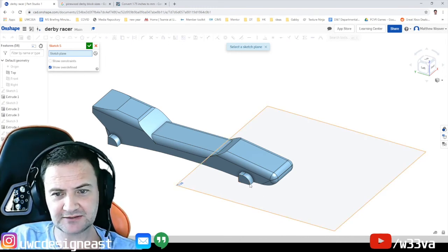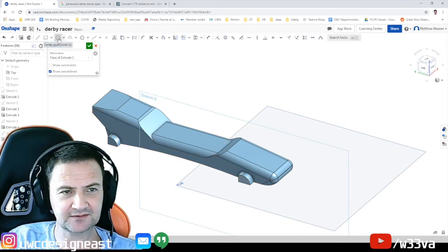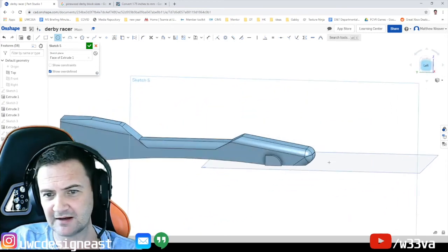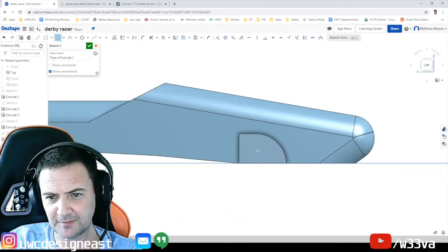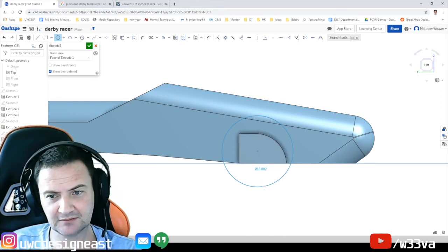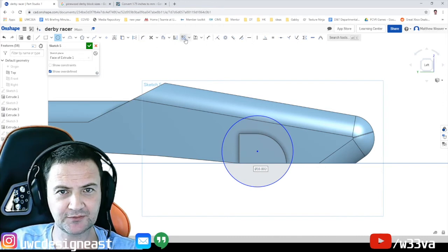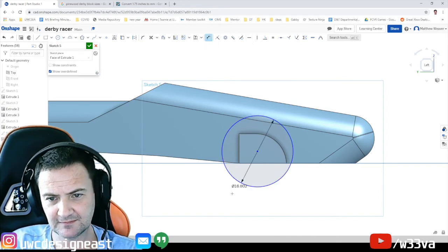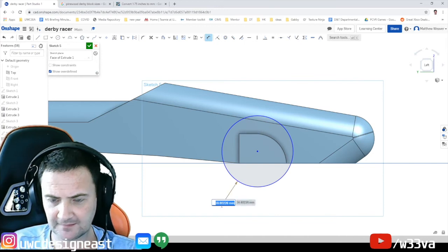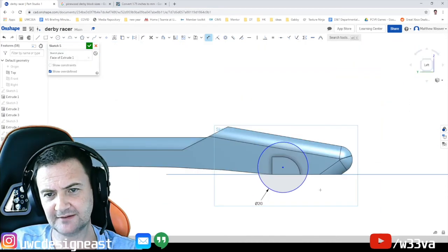So if we go new sketch, select that face, there's your sketch 5, and of course it's a circle. Look directly at it, makes your life easier. Zoom in, the center of the circle is going to be there. I think I've given you 20 mils, I think. So if I just go here, then go to dimension, and type in 20, press enter, and that is our wheel.